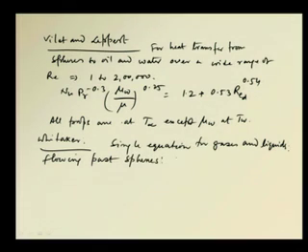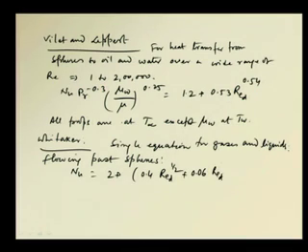According to them, Nusselt is equal to 2 plus 0.4 Re_D to the power half plus 0.06 Re_D to the power 2/3, times Prandtl to the power 0.4 times (mu by mu w). Okay.